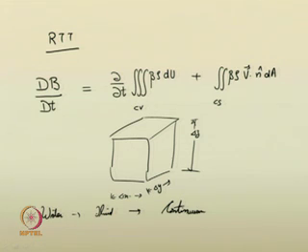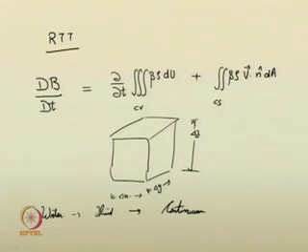So, the material derivative of that extensive property is nothing but the time derivative of the net extensive property generated or lost inside the control volume plus the net outflux, considering both outflux as well as influx, of these extensive properties across the control surfaces.